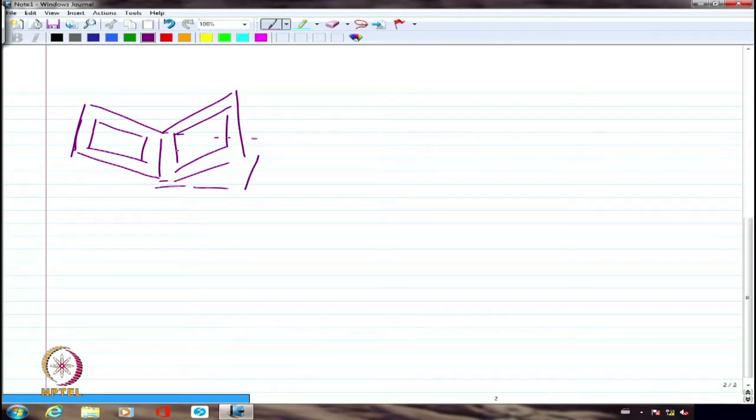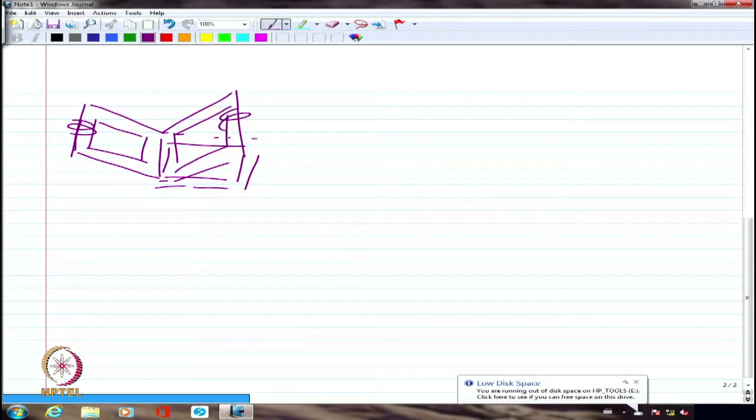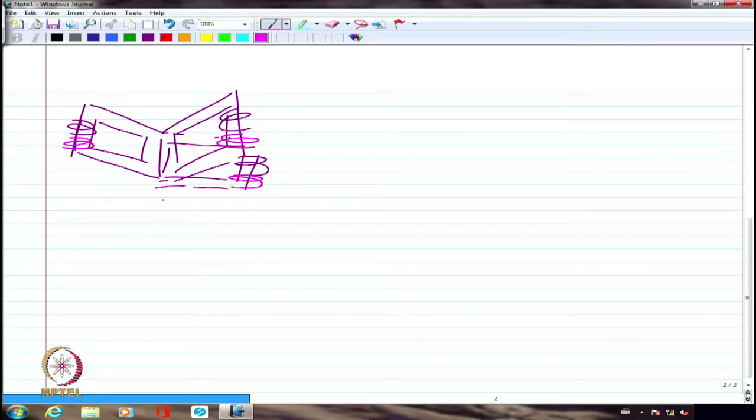I hope you understand. There may be three such cores which are something in the shape of a Y or something like that. So I have three such cores. So I'm going to have maybe the windings wound here. This is primary. Similarly, maybe this is primary. Similarly, this is primary. Whereas secondary may be wound, I'm just showing as though it is not even wound in the middle limb at all. I can still have something wound on the middle limb, which is actually working as the anchor point for all the three branches, but I might choose to wind the winding only in these branches.